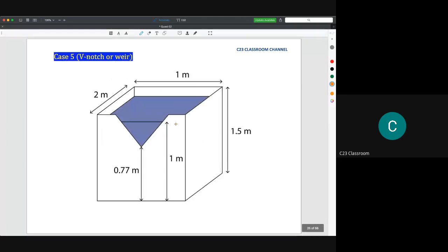Okay, so that means up to now you have seen that the idea is easy. First we develop the equation for the outlet velocity. Rule of thumb, please do not substitute the initial height, because if you substitute the initial height, you will get the value of velocity outlet, and then you cannot do the integration process.